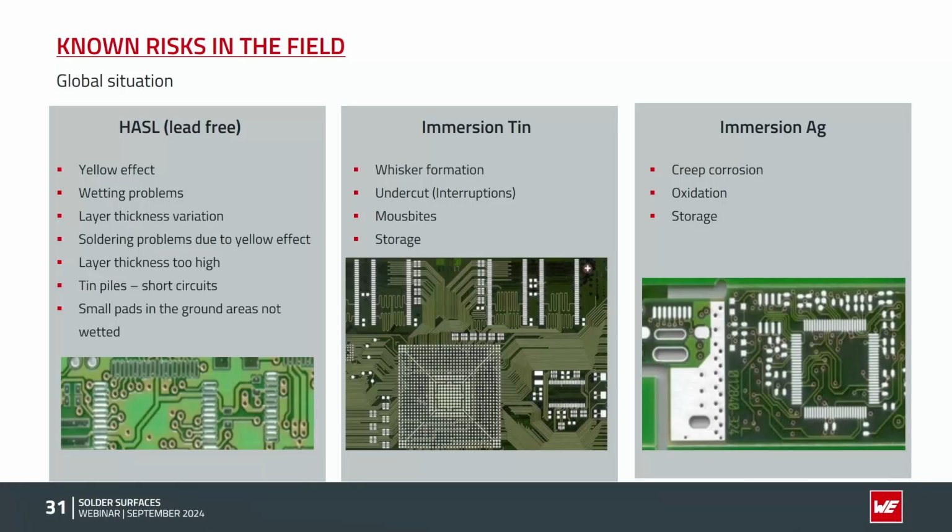That's not fine, but you have to know this. If you apply temperature to the board, the whiskers will disappear. But if whiskers break and produce a short, that might be critical.